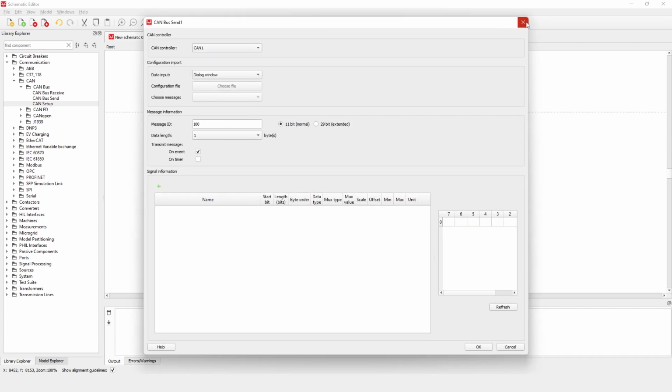As always, you can continue using the set of CAN-FD components to establish a CAN-FD communication. However, keep in mind that while the CAN-FD communication channels are available for both CAN and CAN-FD communications, these channels cannot serve both communication protocols simultaneously. With this change, we aim to expand your possibilities for controller area network interfacing.